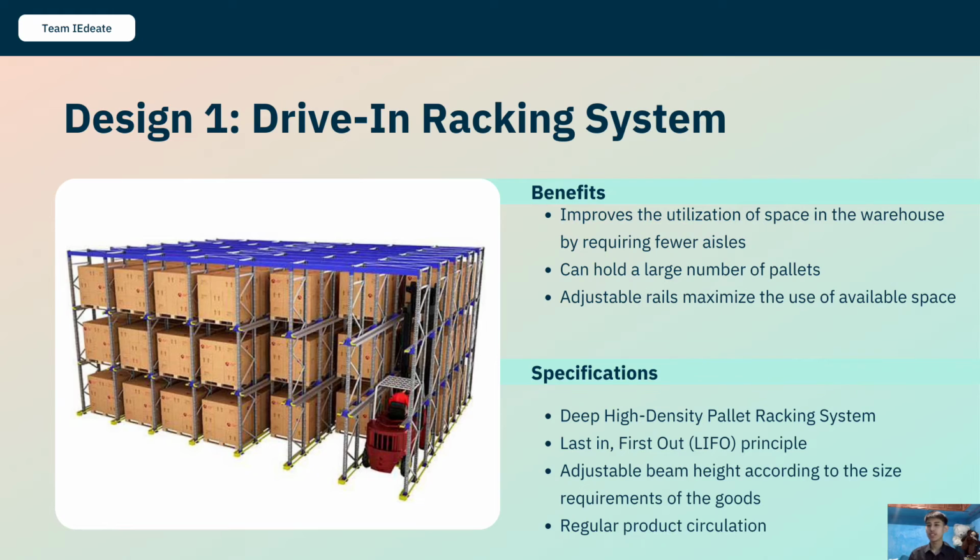Design 1 is the drive-in racking system. It is a deep, high-density pallet racking system. Last in, first out principle. It has adjustable beam height according to the size requirements of the products. And lastly, regular product circulation.